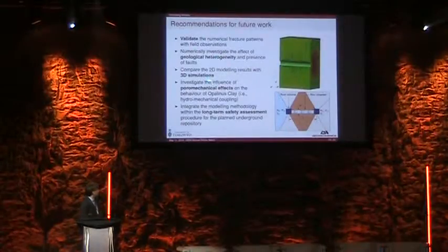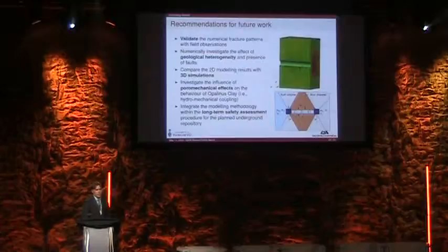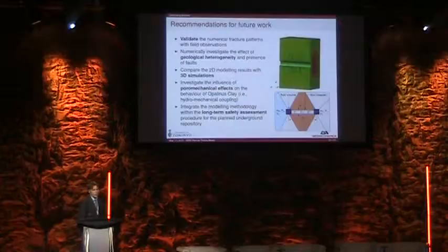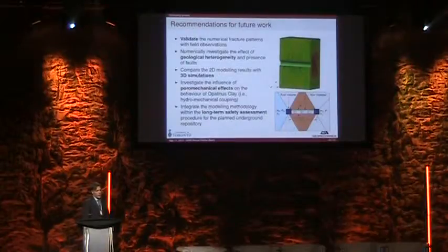We definitely need to go to 3D modeling. Something has already been done in this sense, especially to look at the effect of the excavation, what happens ahead of the excavation phase. Another important aspect that was neglected in my work is the pore fluid pressure, so coupled hydro-mechanical effects should be incorporated into this kind of model. Some work has also been done in this regard, looking at how to integrate this result into long-term safety assessment for the underground repository.